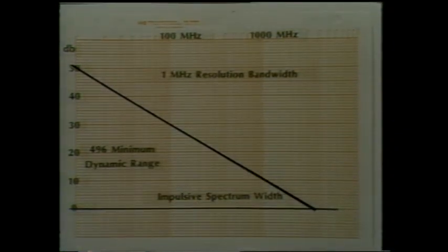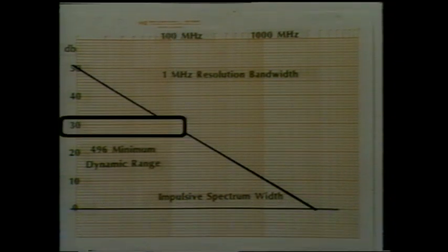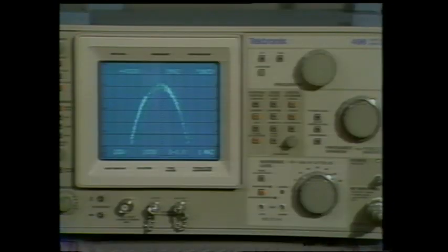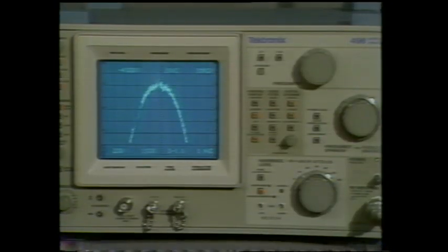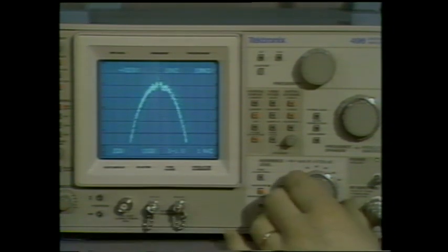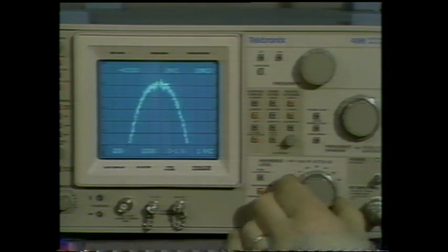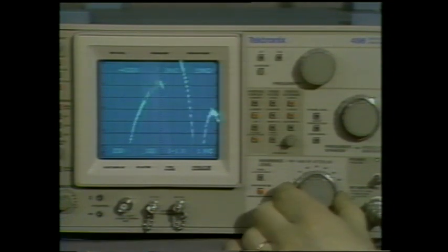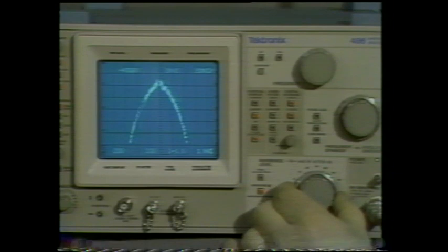Most interference, though, is around 100 megahertz wide. This would be a 40 dB difference, leaving about 30 dB dynamic range. Excellent. To measure whether you're in trouble on overload, change the mixer drive level and see if the measured level changes. If it doesn't, you're safe. Changing the minimum RF attenuator from 10 dB to 20 dB, the display level doesn't change, so we're okay. Going down to 0 dB minimum attenuation, there's a slight change in signal display level. Some compression right there.